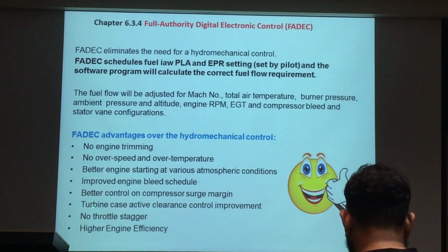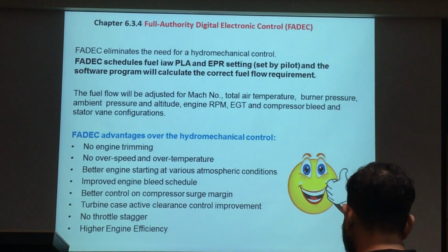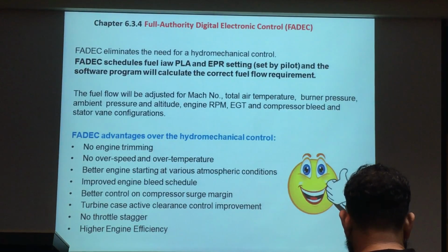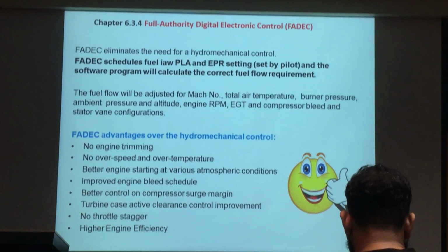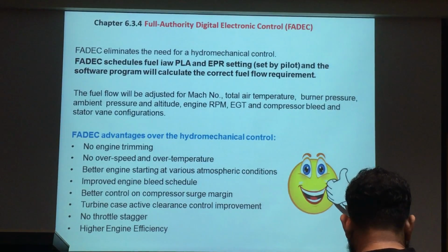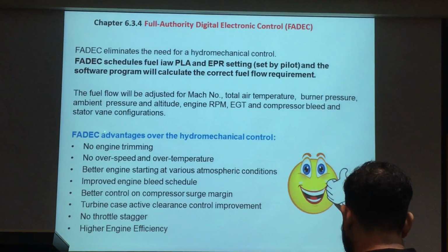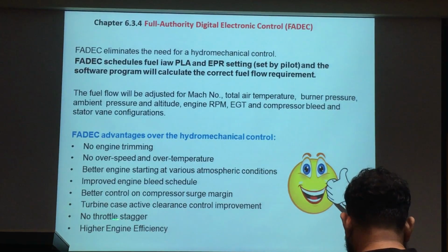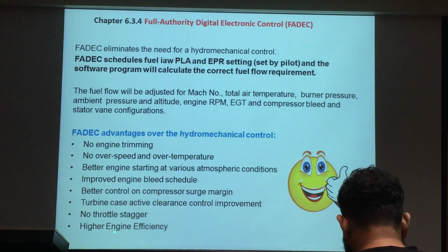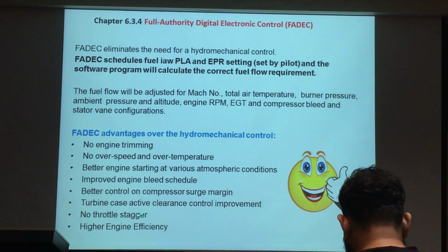The turbine case active cooling, remember the ACC cooling? Turbine case cooling uses what cooling air? It uses fan air to cool the turbine case, not the turbine blade. And this is controlled by your FADEC, giving higher efficiency. A lot of advantages. This is the seven basic ones.